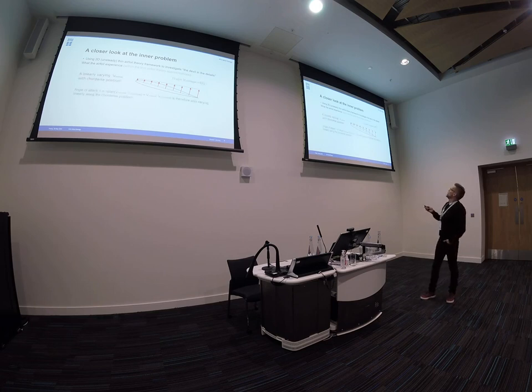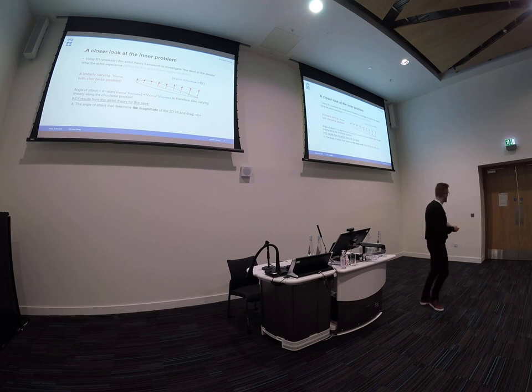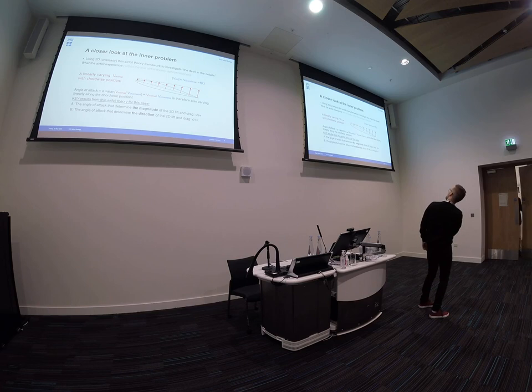is when you do all this thin airfoil stuff, three important things pop up. One is that the angle of attack, which you should measure to look up the lift and drag data, should be evaluated at the three-quarter point here. And the relative flow direction determines in what direction you put the lift and drag on. Drag is in the direction of the flow at this evaluation point, but there you need to use the directions of the flow at the one-quarter point.